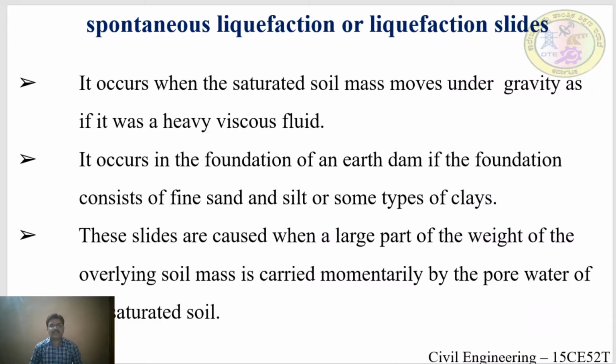This is the next slide where spontaneous liquefaction or liquefaction slide occurs. It occurs when the saturated soil mass moves under gravity as if it was a very heavy viscous fluid. It occurs in the foundation of an earth dam if the foundation consists of fine sand and silt or some types of clays.